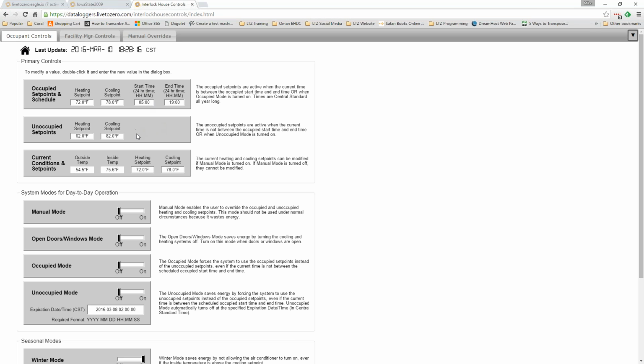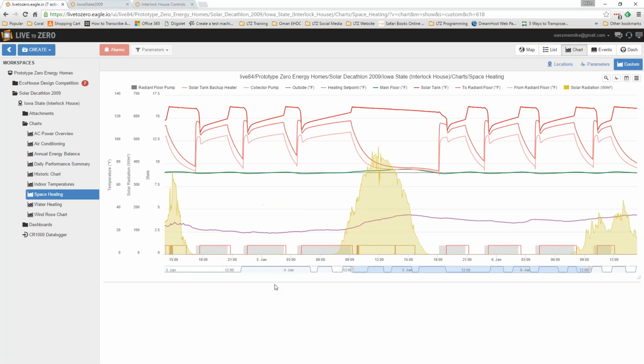But that's not part of the current algorithm. So that capability is not in there right now. So instead, for simplicity, during the winter, I figured this is also easy to calibrate a model against, is just leaving the set point at 72, not touching it, and then we have a lot of good data through a winter to calibrate the model against. But next winter, we might want to think about trying to optimize things to start saving energy.